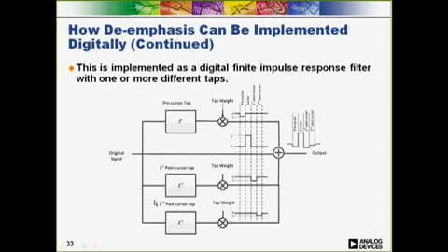In this example, you can see that the precursor tap weight is -1/4. You might be able to see that. Anyway, that's just showing the amplitude of this signal here is -1/4 the original, which is here, and it's at a negative delay.